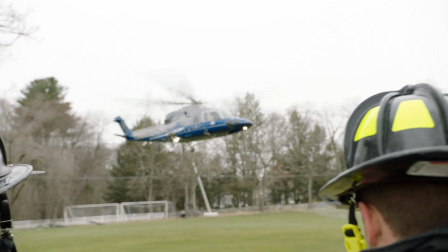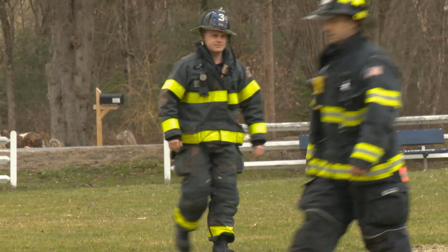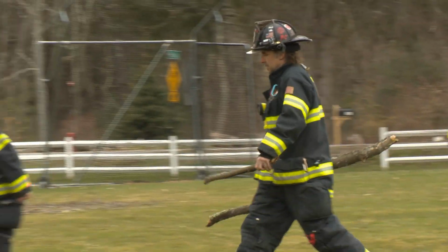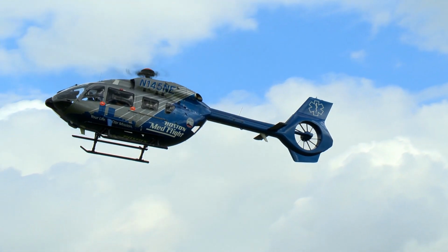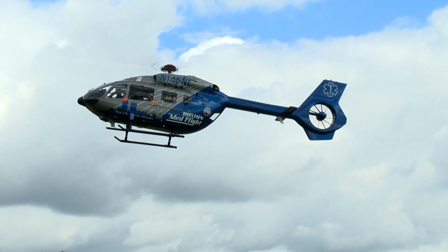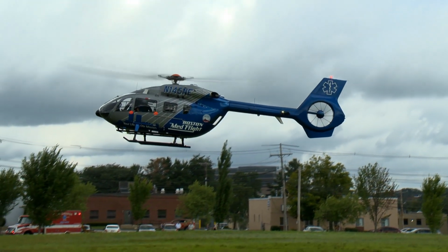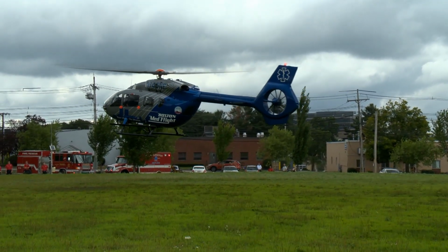Ground personnel should abide by the landing safety procedures. Immediately upon arriving at the LZ, ground personnel should either remove or secure all potential debris. The helicopter always needs a clear angled approach corridor. The aircraft will typically approach the LZ heading into the wind and on an angled descent to the ground. The helicopter does not descend straight to the ground from a high altitude.